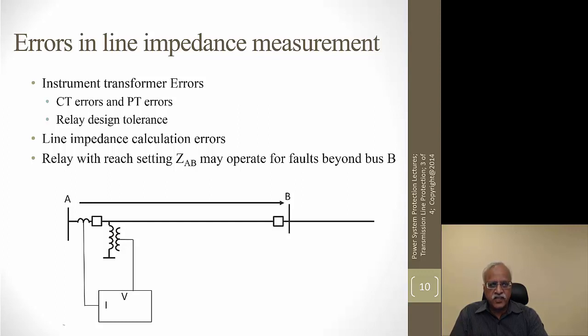And the measurements in the relay itself have some accuracy. If you look at this, with the line impedance calculations, you cannot go from point A to point B and detect accurately for faults at point B. We don't know whether it is on the line or behind the breaker at the remote end, or beyond the line section AB if it is very close to station B.